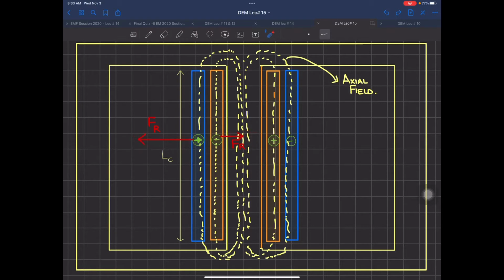So what is happening? In a short circuit, the inner winding, which is actually the low voltage winding, is crushing the core. The outside winding is actually being thrashed out. Now, if they both were happening in the same direction, they would cancel their effect. But now it's not happening. This inner winding is going to compress the core, and the asbestos cylinder or the insulated cylinder that we put on a stepped core to make it full circular, that is going to be crushed.